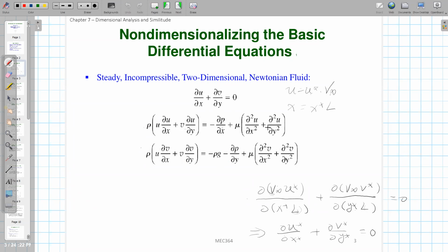Okay, and when you analyze a problem, sometimes you want to see whether or not this viscous force is significant, right? So for example, for some flow, if I want to assume the flow is inviscid, can I do that or not? It depends on whether this term is larger or smaller compared to the other two, right? If this term is much larger compared to this one or this one, you cannot neglect it. And if this term is smaller compared to these two, you can neglect it, right? But how can you know whether they are larger or smaller?